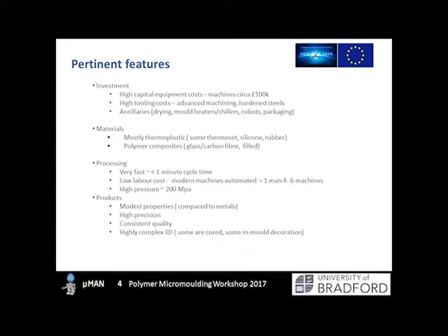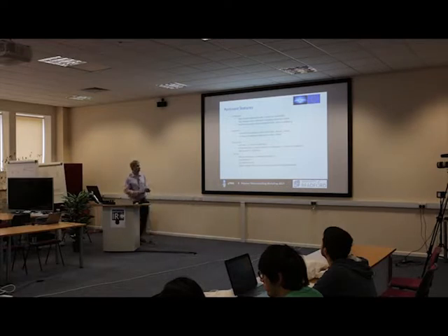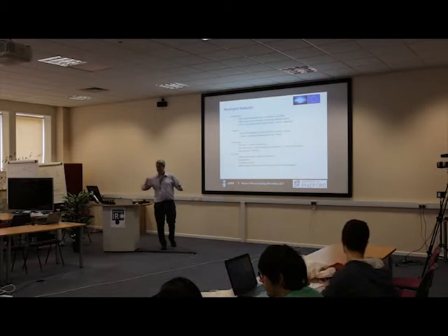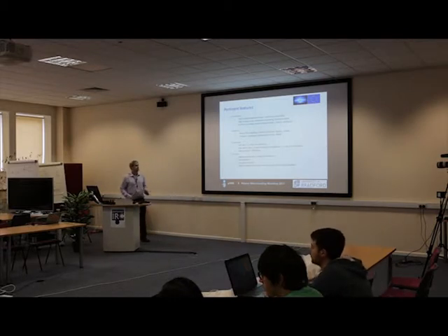You've also got to have additional capabilities like material handling capabilities, drying capabilities, that kind of thing in your factory. But the main thing here is the materials we're using are actually comparatively cheap. Adrian discussed the benefits of thermoplastics yesterday, in that they're easily formable and have good mechanical properties, but overall the cost is pretty good. And we can make them extremely quickly as well. So even for the large parts, we generally have less than a minute cycle time for one of these machines to make each component. For the smaller parts, that can come down to just a few seconds in many cases.